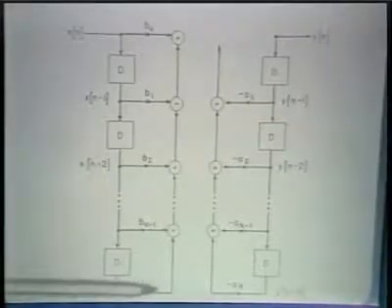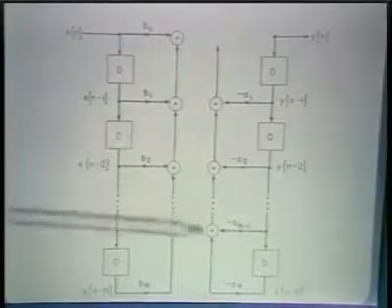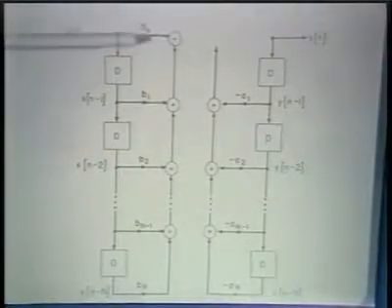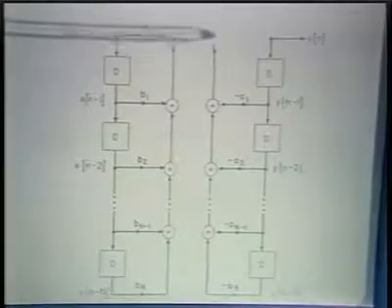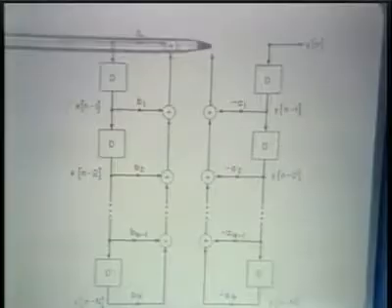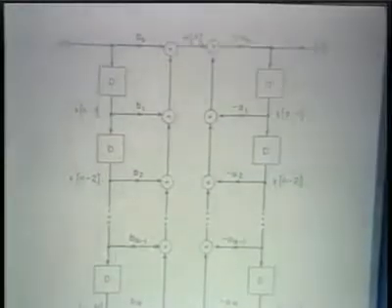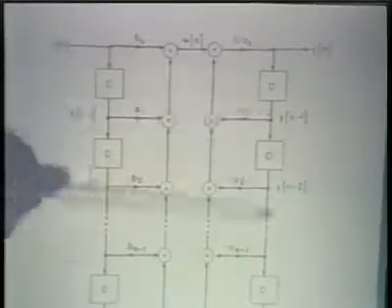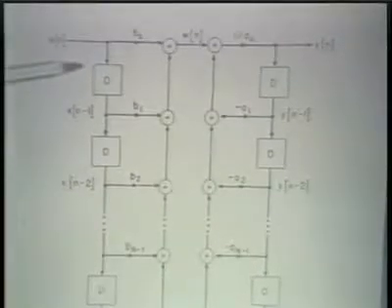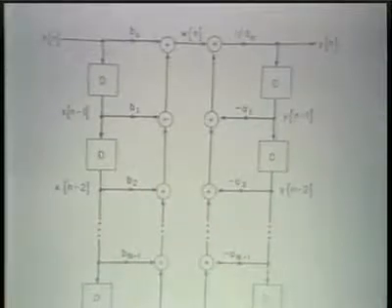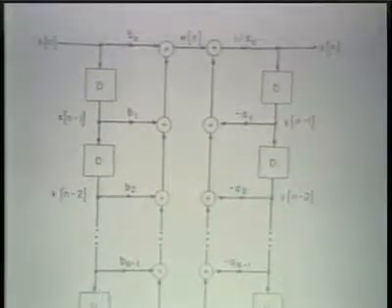And so we now will sum these, and we'll sum these. After we've summed these, we want to add those together, and there's a factor of 1 over A0 that comes in, and that then generates our output. And so this, in fact, represents a general block diagram for implementing or representing a linear constant coefficient difference equation.